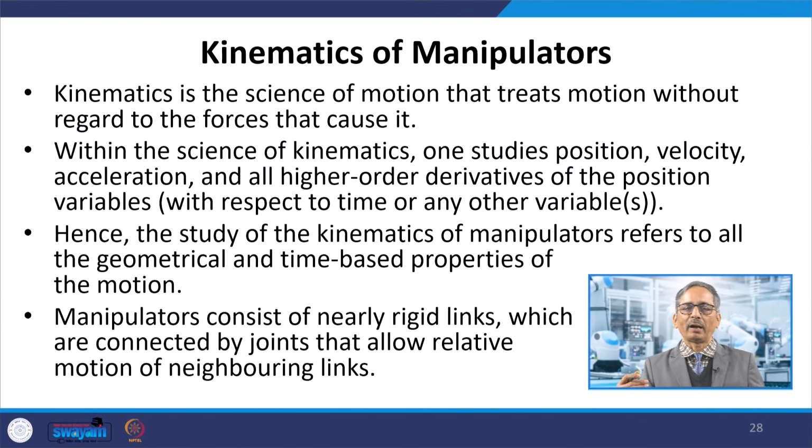Then coming to the kinematics of manipulator, as all of you know, kinematics is the science of motion that treats motion without regard to the forces that are causing the motion. And here in kinematics, we study basically the position and its derivatives, which are velocity, acceleration, and other higher order derivatives, and naturally these derivatives are of position with respect to time. So here basically our aim is to study all the geometric and time-based properties of the motion.